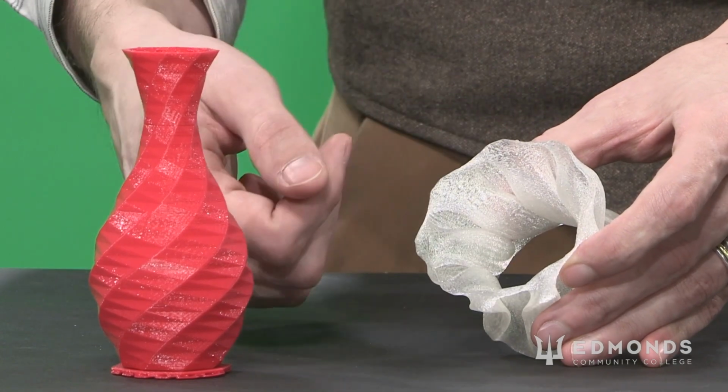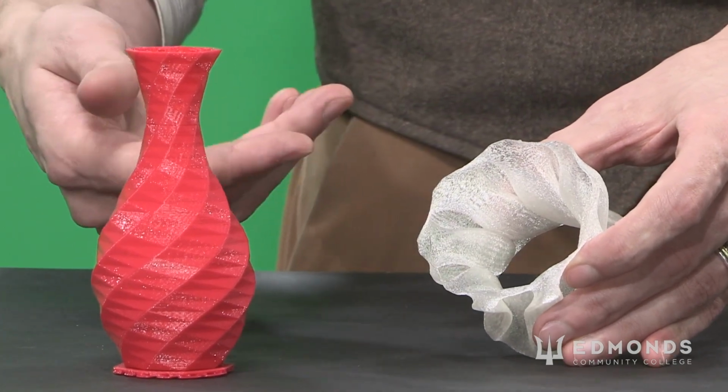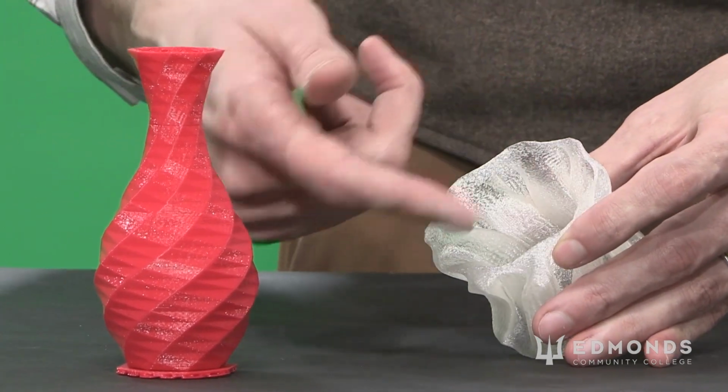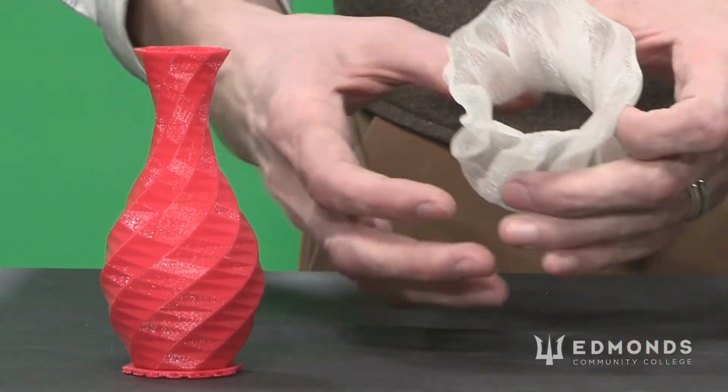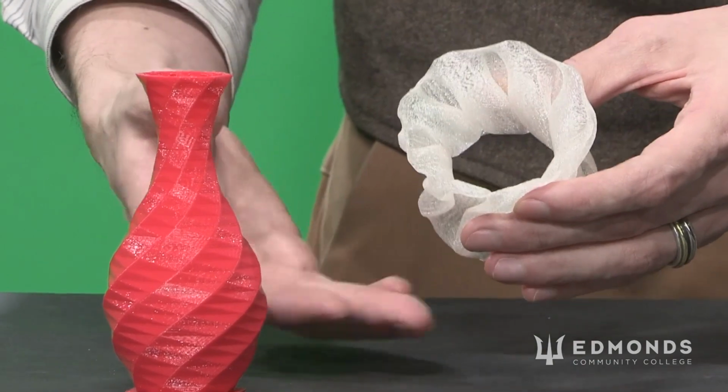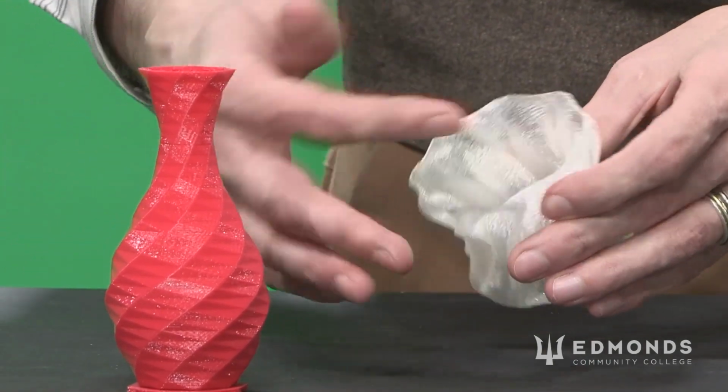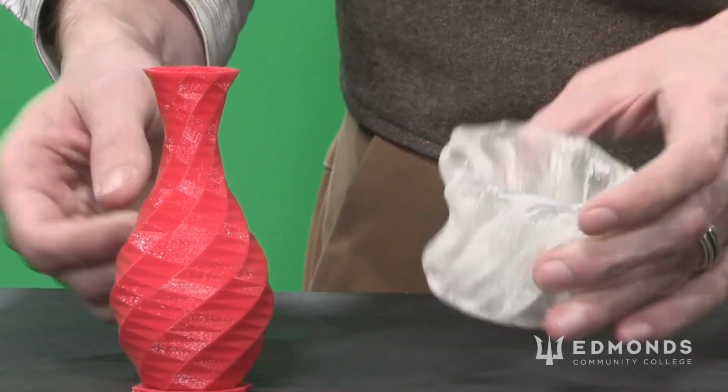The tip never has to pick up. It simply changes between layers. It never has to move across empty space. It essentially never has to stop moving. And that also means that by never stopping moving, we never really get any change in our flow properties.